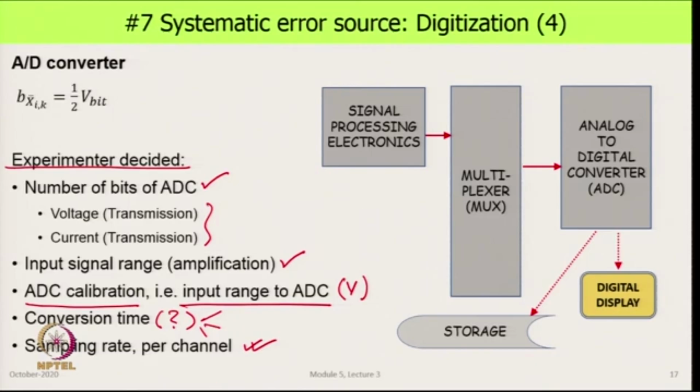If we were looking at a multiplexer, the A to D converter will take this signal, digitize it and put it out. Then it will give a signal back to the multiplexer to say that I am ready to take channel number 2, send it. So, it will then disconnect this, connect this and convert it into a digital signal. Then it will send a signal and say I am ready for channel number 3, this gets disconnected, number 3 gets connected and now this gets digitized. So, like this it goes through all the channels and then the cycle is repeated.